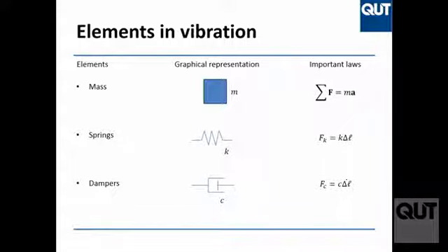But vibration itself is a problem sometimes. Imagine you have a building and there's an earthquake; the building will vibrate following the earthquake. If it vibrates too much, what happens? Internal stress is high, because big vibration means big deformation of the building. Do you agree? Big deformation means big stress. You know that sigma equals E epsilon, right? So big epsilon, big sigma. Big stress means failure.